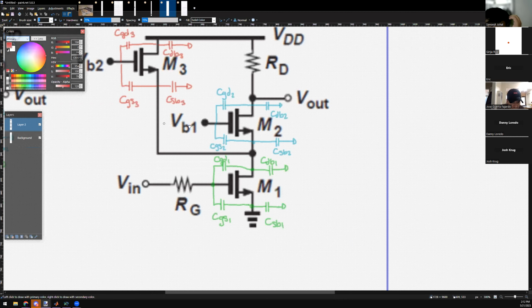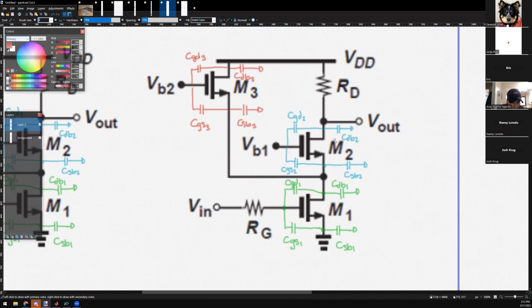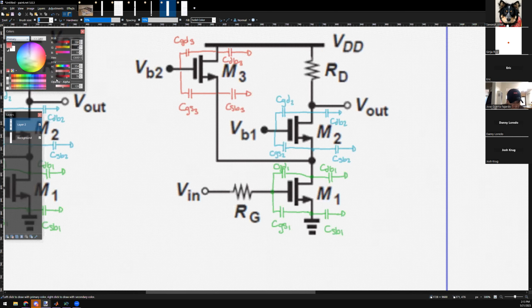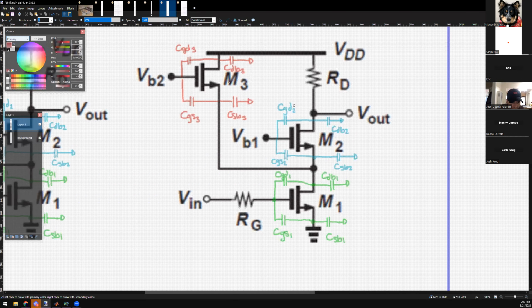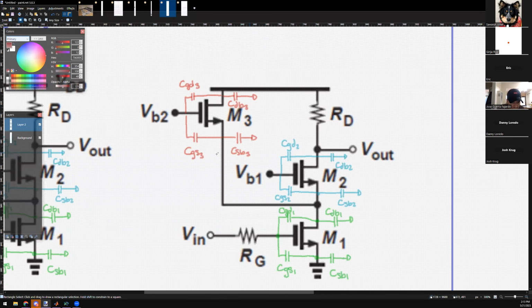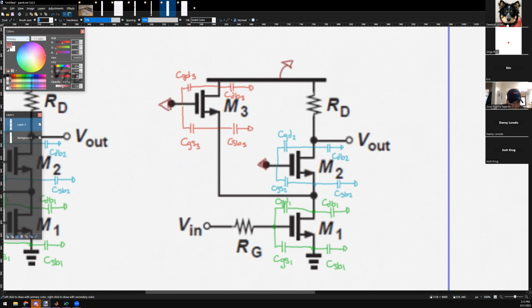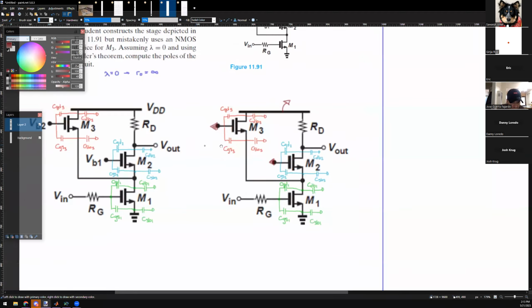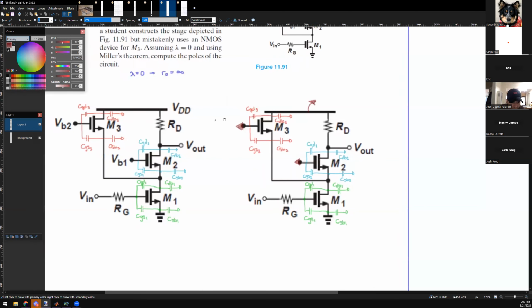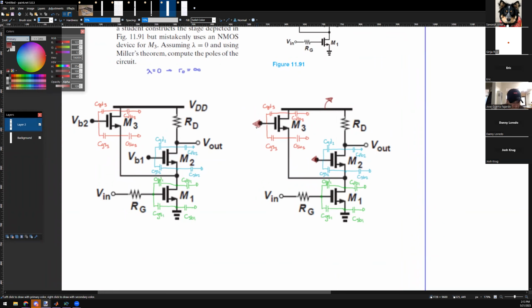Good. Okay. So from here, we have tons of things that we can eliminate. For example, things that are AC shorted. VDD is now AC shorted. V bulk is AC shorted. Bias 1 and bias 2 are AC shorted. So I can AC short these guys, and AC short these guys. Are you going to AC short first and then draw the parasitic capacitors, or are you going to draw first? Order doesn't matter because I haven't made the simplifications yet. Okay, sounds good.